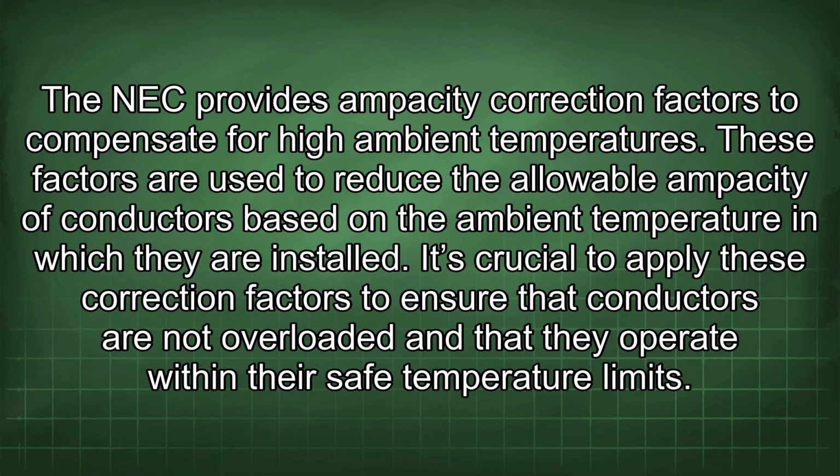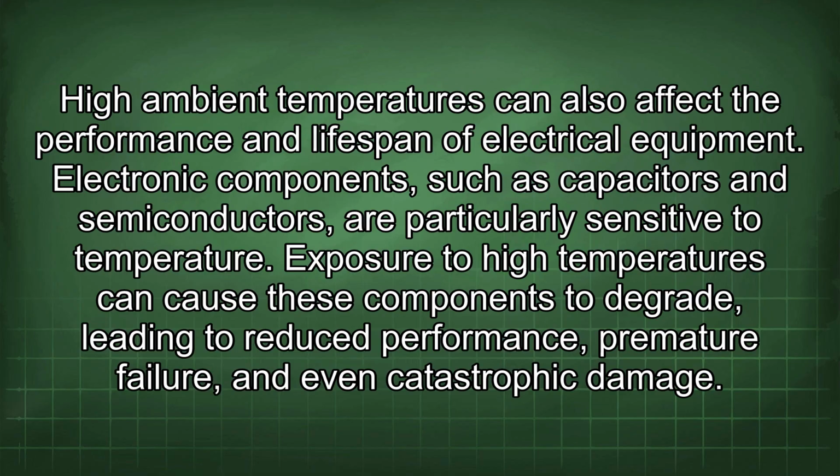These factors are used to reduce the allowable ampacity of conductors based on the ambient temperature in which they are installed. It's crucial to apply these correction factors to ensure that conductors are not overloaded and that they operate within their safe temperature limits. High ambient temperatures can also affect the performance and lifespan of electrical equipment. Electronic components, such as capacitors and semiconductors, are particularly sensitive to temperature. Exposure to high temperatures can cause these components to degrade, leading to reduced performance, premature failure, and even catastrophic damage.